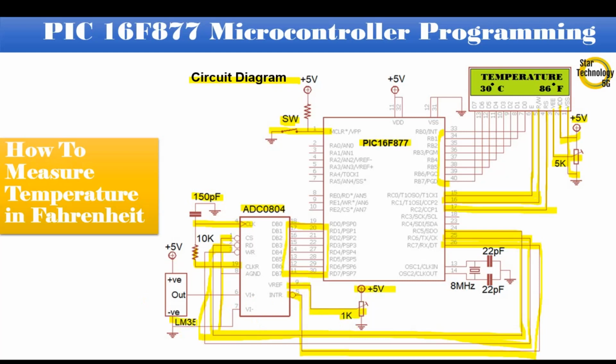It is LM35 temperature sensor. Positive pin connected with positive 5 volts. Negative pin connected with ground. Output of the LM35 connected with analog input pin of ADC0804.